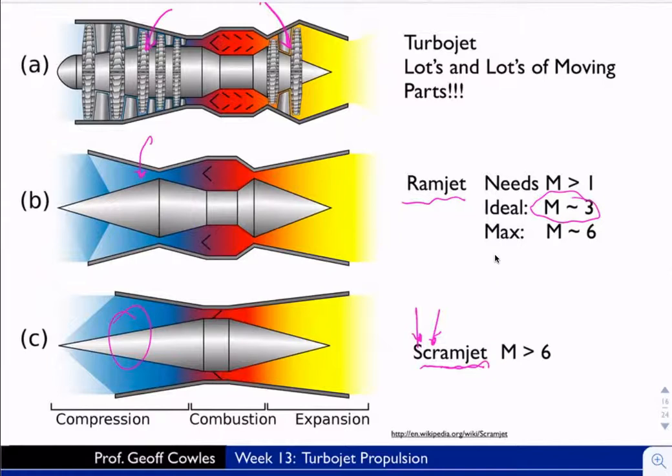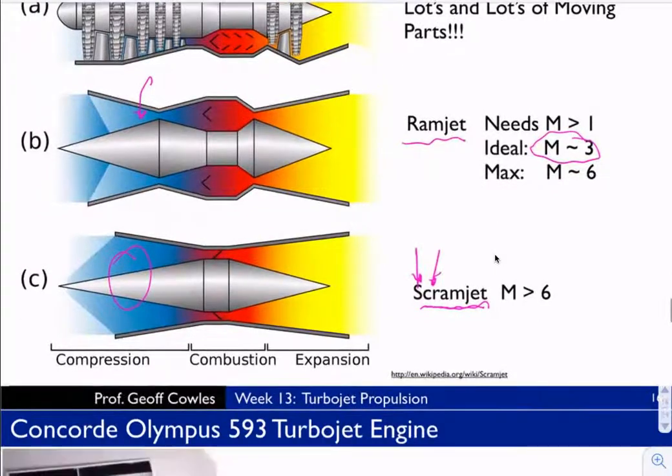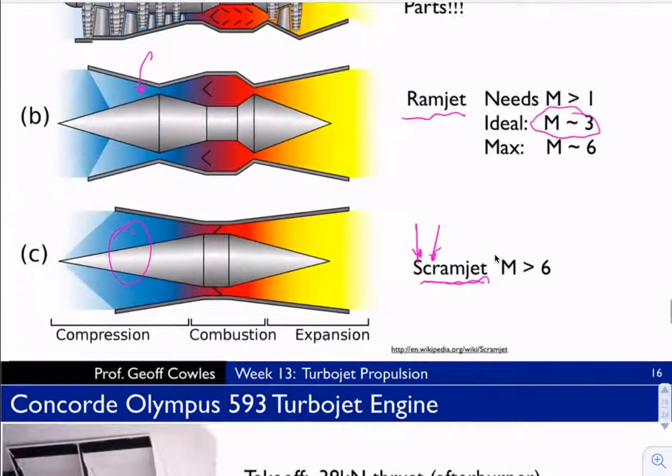I forget what the SR-71 engine is. It's something like a J58. I'm sure it's on Wikipedia, and they would probably have a picture better than I can explain of how that engine functioned both during takeoff when you need maximum thrust at subsonic velocity, so you need actual compression from compressors, and then later when it's flying at Mach 3 plus, how it's able to produce thrust.